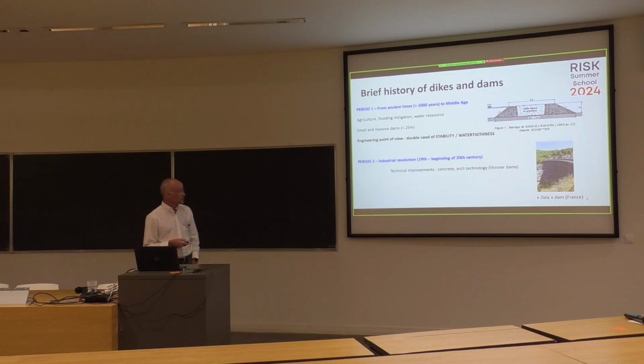So from a practical point of view, the well-designed dams are, as illustrated in this picture, made of 2 parts. The central part is made with clay or a very impermeable soil to ensure the water tightness. And on both sides, you can find rockfills that ensure the stability.